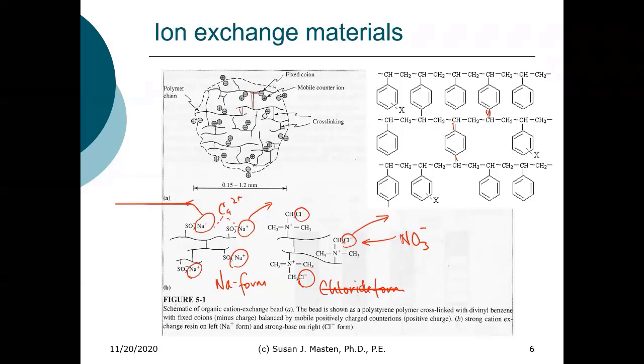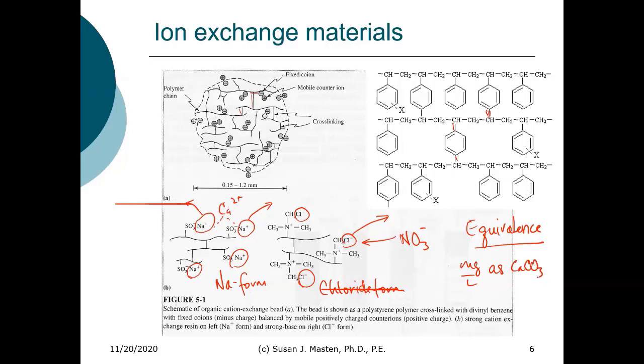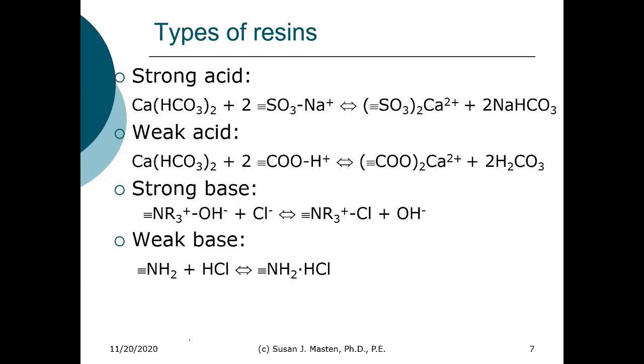So when we talk about ion exchange materials, we will talk about equivalence. We can also use milligrams per liter as calcium carbonate. We need to maintain charge balance. We can have resins that are strong acid, weak acid, strong base, or weak base.